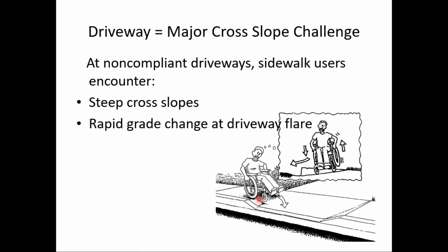Notice in negotiating this driveway flare, the small front wheel of this wheelchair is off the ground, and that is an undesirable situation. We want our designs to be such that at all times, all four wheels of the manual wheelchair are on the ground. So this is not a good situation from a safety standpoint.